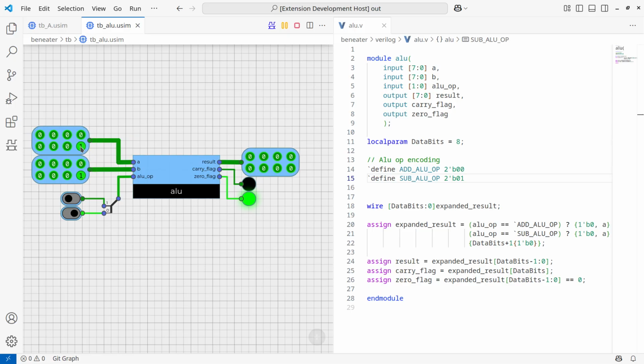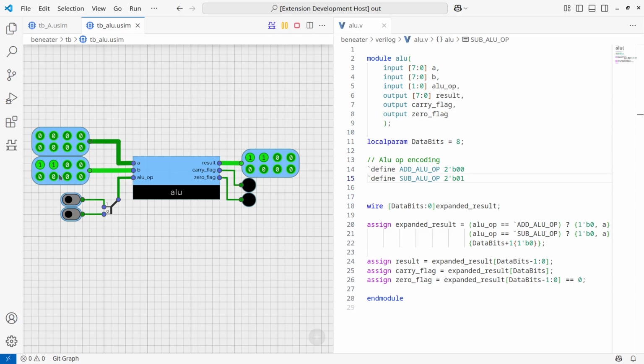So now that we have this, we can check if the carry flag is working. In order to have a carry, what we can do is have a big number, maybe like this, and we add another big number, I think. Oh yeah, sorry. So yeah, it's overflowing now. Now it's not overflowing. Now we overflow. And yeah, if we do this, it's even an overflow on this. Exactly. So we have 0 plus this value, so we have a positive value. If we do this, we have a negative value, so the carry flag is set on. Great, wonderful.